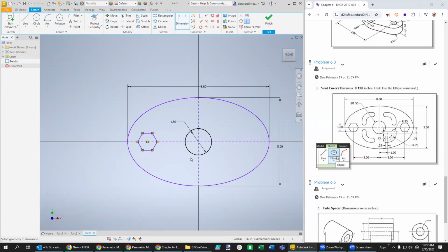And the size of this one is going to be 1 inch from top to bottom. So from that point to that point, coming off to the side, 1 inch. Its placement relative to the center is going to be 3 inches. So you see our systematic approach here is to try to get that one fully defined. And I'm kind of wondering why it's so purple.